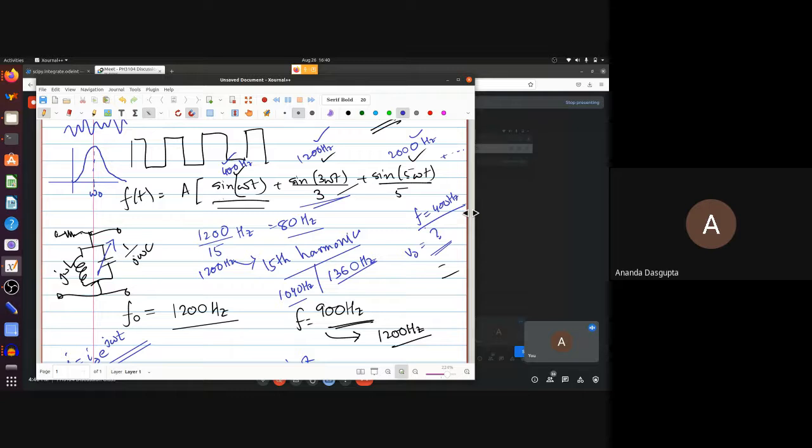Have you heard of the skin effect? When high frequency signals travel through a metal, they do not go in very much. They actually travel mostly in a narrow region very close to the surface. As a result, the effective cross section of your wire goes down. So for high frequencies, the wire essentially looks like a very, very thin wire. Even if you have a thick wire, the core is almost untouched. The current doesn't flow through the core. It flows essentially through the surface.